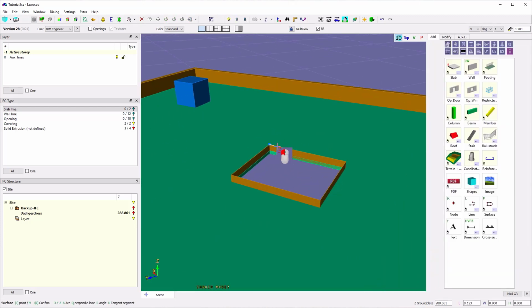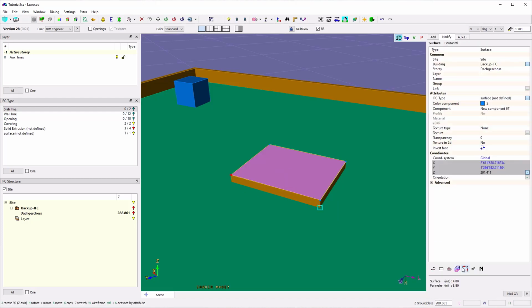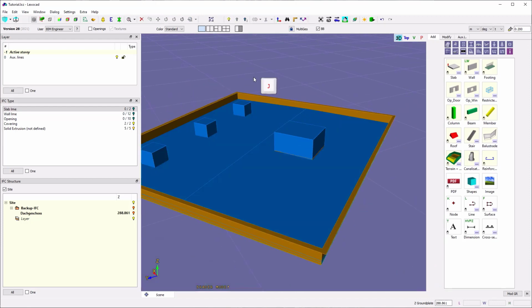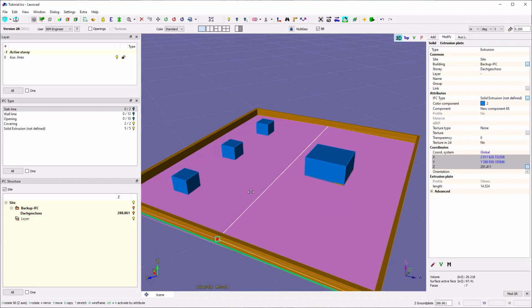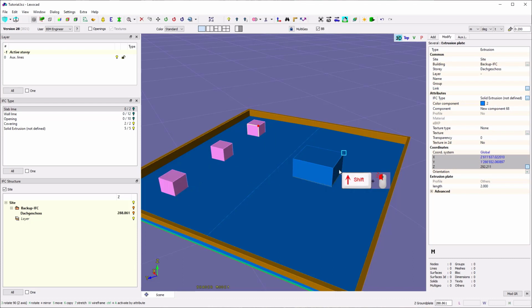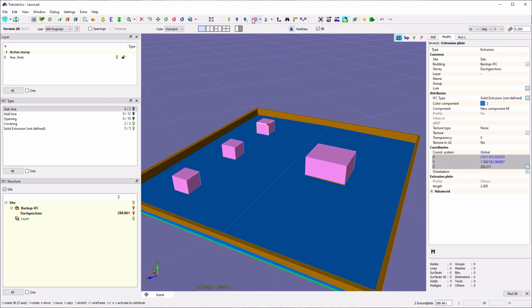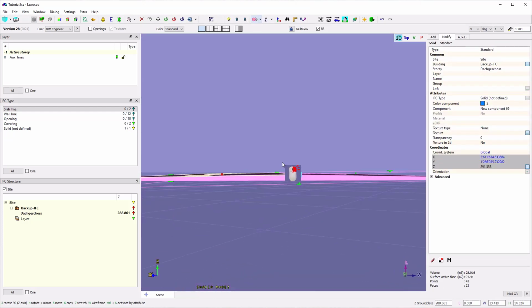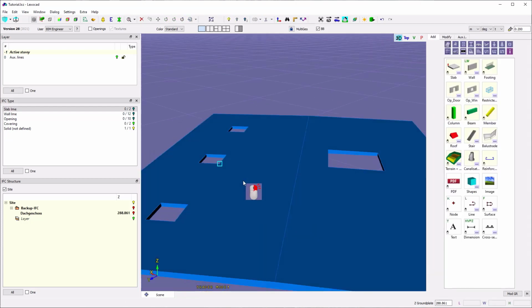We do the same here, click the surface with F, so 2 meters, and go a little bit. So, and now with J we got here our slope element back, and now we activate all of our elements to cut, and then we use here this cut function on the toolbar and cut it here. The active elements we can delete, and now we see we got our slope element with our angles and the holes in it. Perfect.